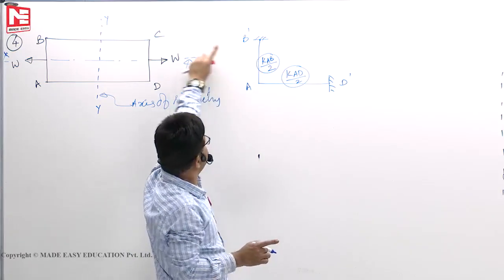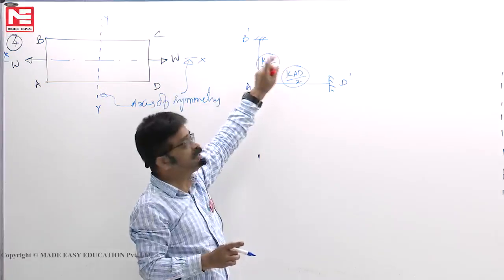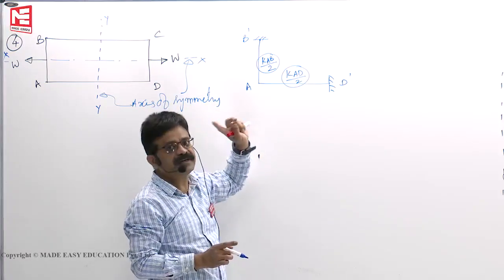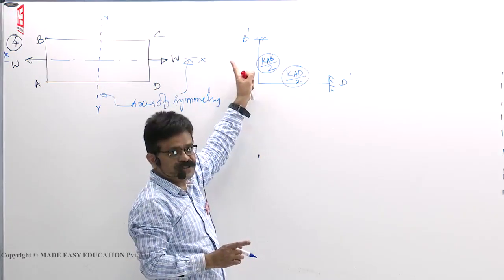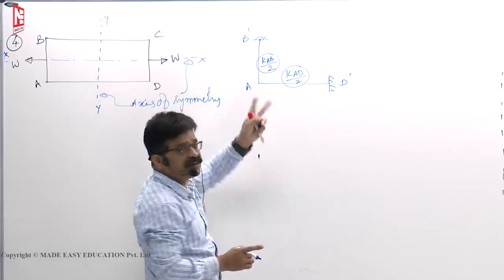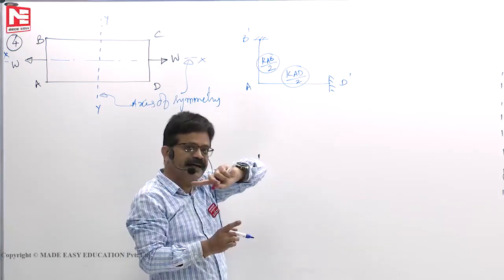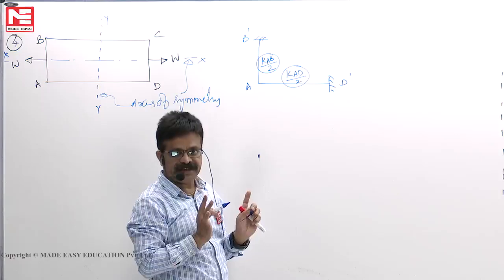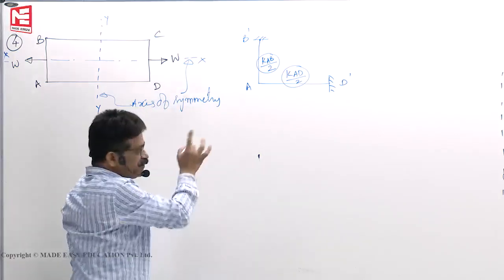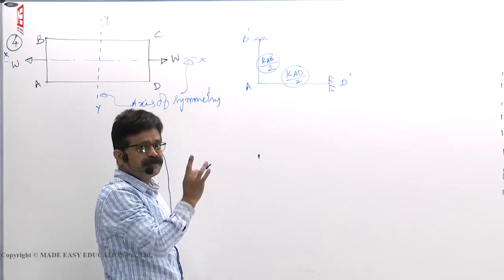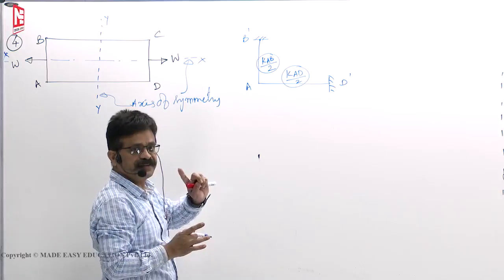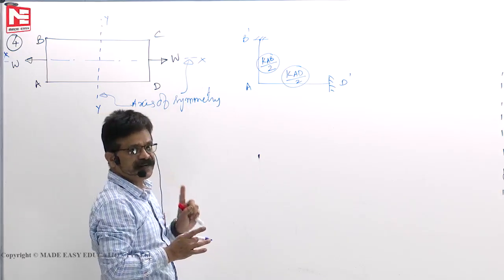When you are calculating the fixed end moments due to load, this frame we don't use, because for loads, this frame and this frame are not identical. Only for end moments they are identical. Okay, means deflection profiles, we want to get identical profiles, so you can use this way only when moments are applied.